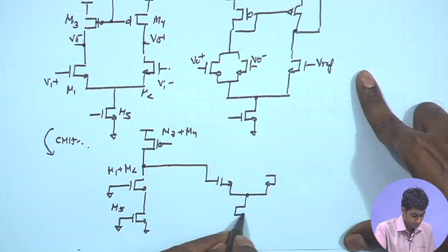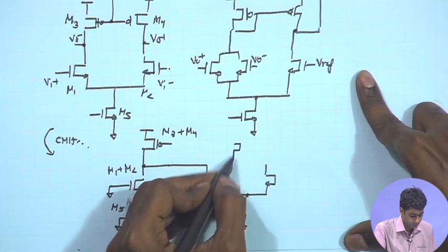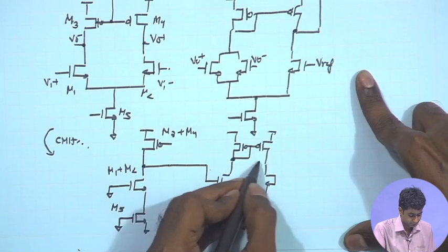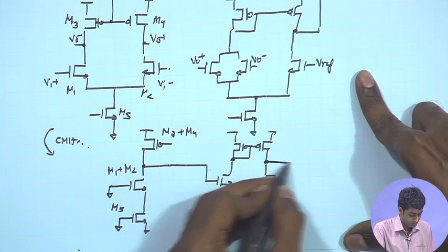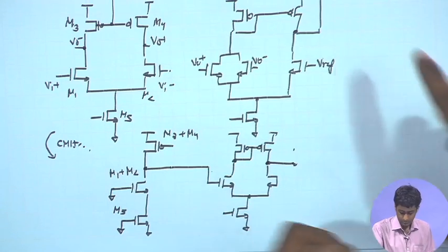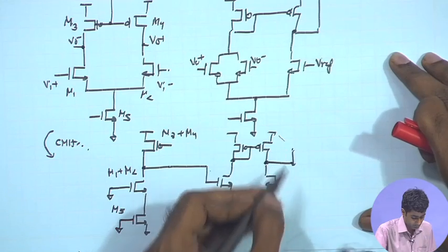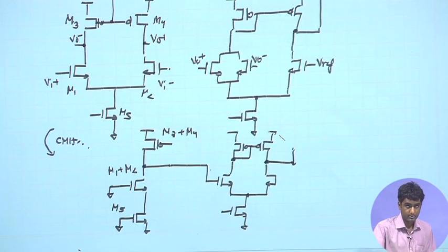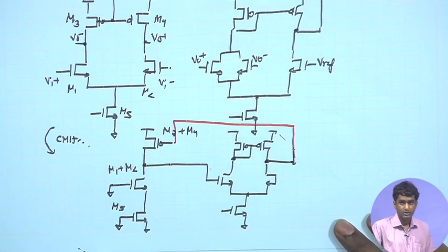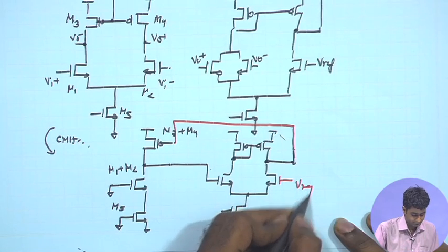and as a result we arrive at a configuration which is something similar to our standard diff amp with current mirror load. And we have our V out basically going to the output using the feedback signal. So, just to keep things separate, and here we have the Vref.